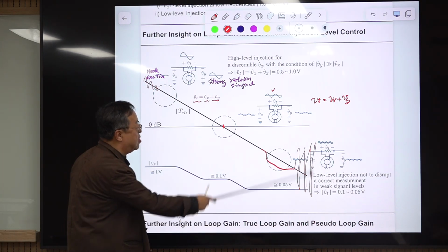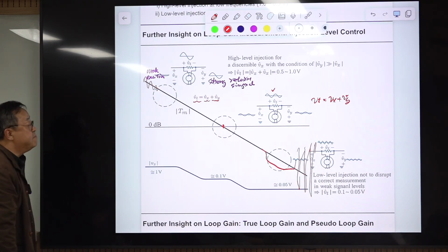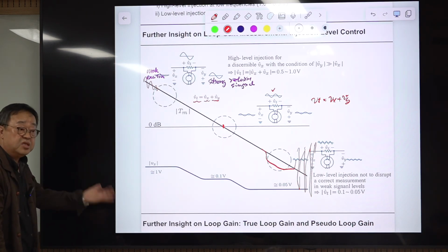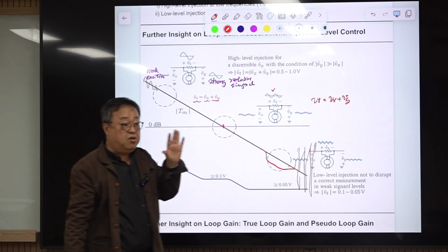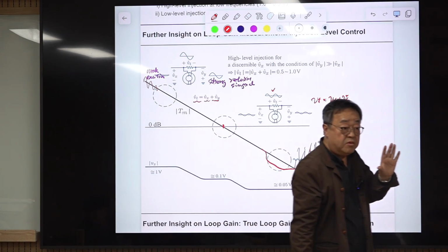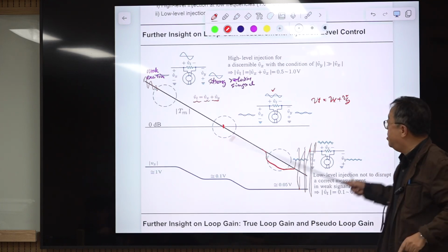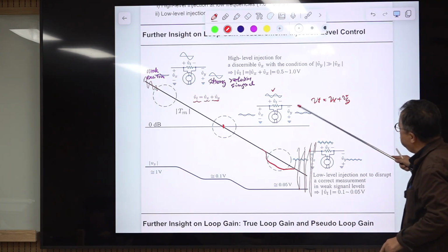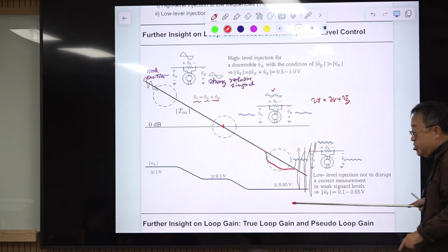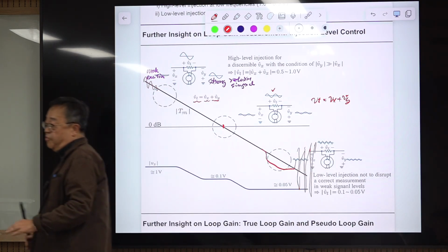And phase is more sensitive to noise than magnitude. So you are seeing very crazy noise in the phase curve. A small change in the slope or direction of the change in the magnitude will cause a huge change in the phase information.